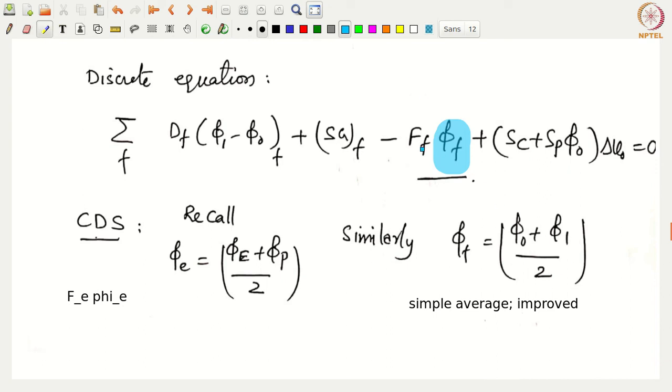Okay, so that's what happens. Now, because of the way ff is defined, this will always be a minus here, because ff already contains the plus minus automatically depending on the area vector. So as a result, we can now substitute for these values and then form the complete discrete equation for the central difference scheme when applied to convection diffusion on unstructured non-orthogonal meshes.